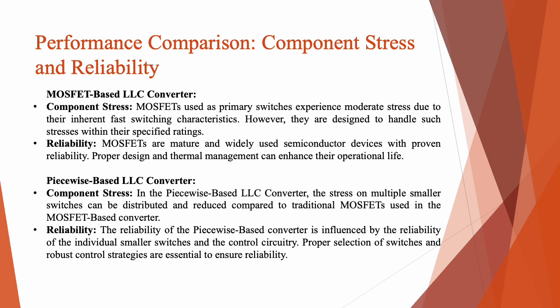In piecewise based LLC converters, the stress on multiple smaller switches can be distributed and reduced compared to traditional MOSFETs used in the MOSFET based converter. The reliability of the piecewise based converter is influenced by the reliability of individual smaller switches and the control circuitry. Proper selection of switches and robust control strategies are essential to ensure reliability.